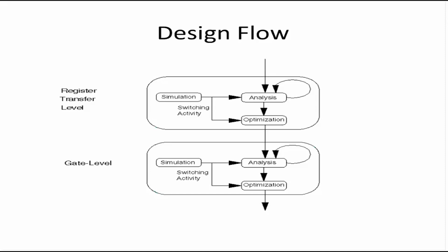So we will exercise the FSM, we will give inputs in such a way that the similar inputs are expected to be given to the FSM in the real world application. So this stimulus will actually determine how much power that FSM would take. Simulation is a very important part of power analysis, because simulation gives us something called switching activity, we'll see the details of it later. So we can use the switching activity for analyzing. Plus, Power Compiler can use the switching activity to also optimize the power, at both RTL level and gate level.